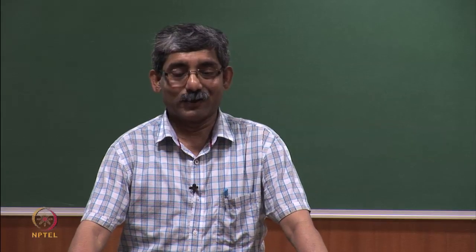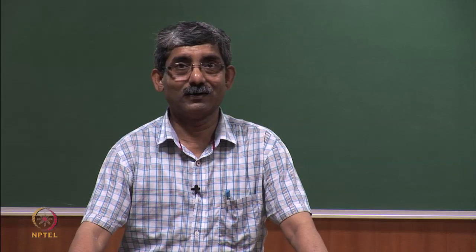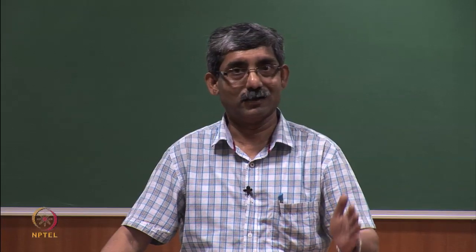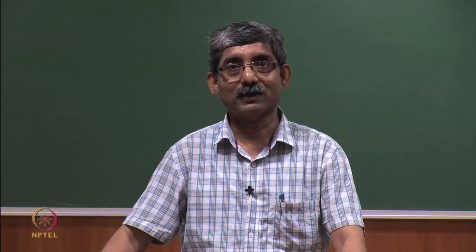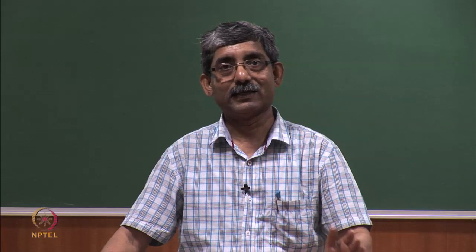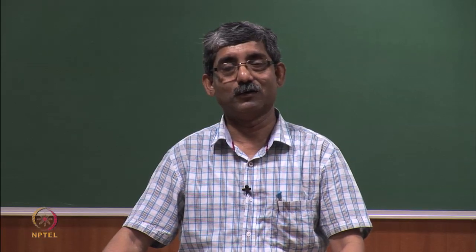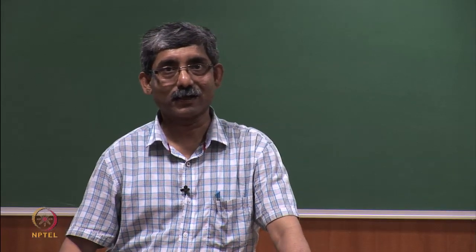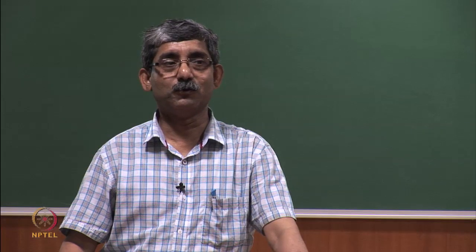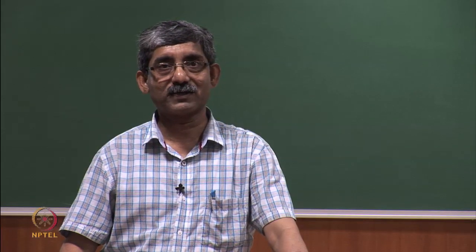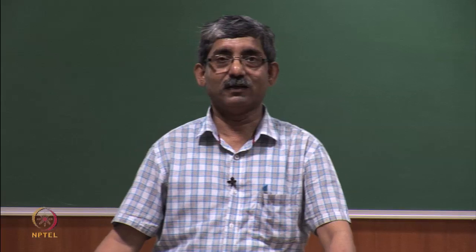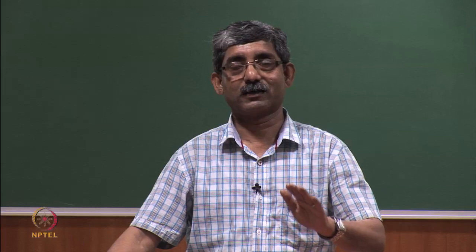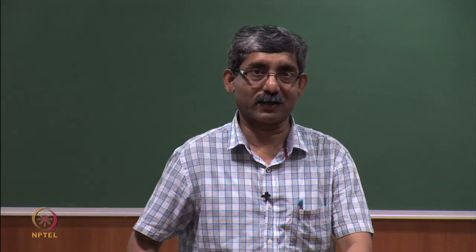So, hello everyone. In the last class we discussed the different modules of the Kawabata Evaluation System for fabrics, KES-F. Module 1 measures the tensile and shear related characteristics, module 2 the bending related characteristics, module 3 the compressional related characteristics, and module 4 the surface friction and roughness related characteristics.